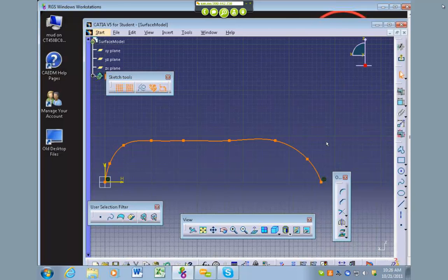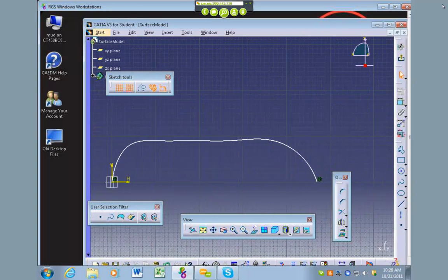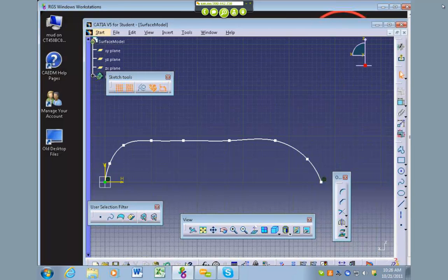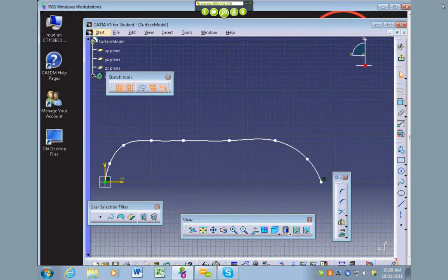You can choose down here to reverse it. This right here will also take the normal too. So if I hit this, it flips around. Right. But you can also use that tool if it's slightly rotated to get back to the straight-on orthographic view. But yeah, if your thing's reversed, you can flip it over and keep sketching that way, and that way it'll get you the right orientation.